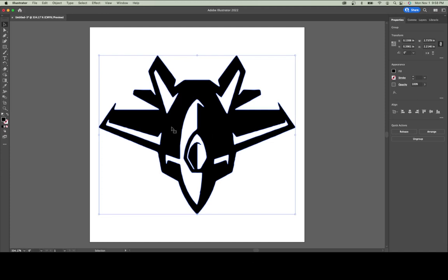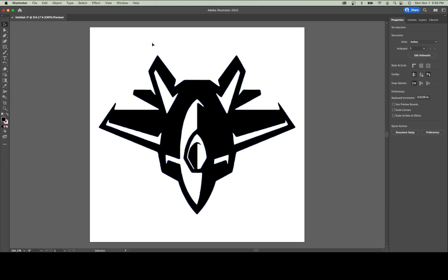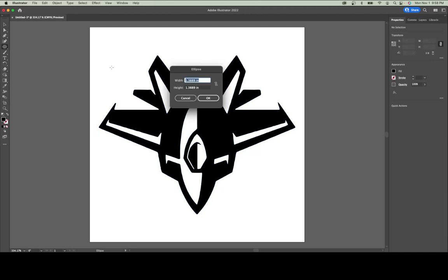So I said that everything in here that's going to be black is what I want to cut out, and that's because those are all the connected shapes. When I actually take this to the laser, what I want to do is actually remove the fill and play with the stroke or the line settings. But first, I said this was going to be a keychain, so I need a way to attach this to my keys. So I'm going to use my basic shapes, get an ellipse here, click on my screen.